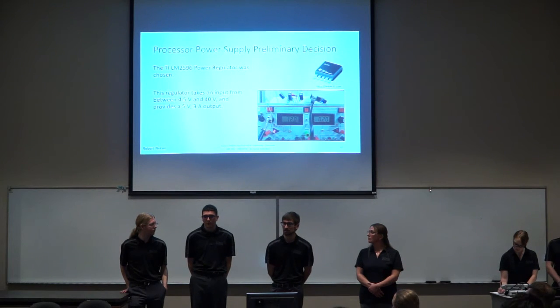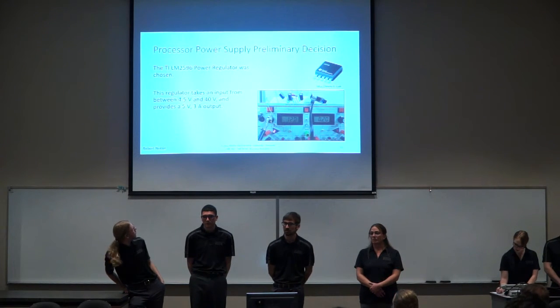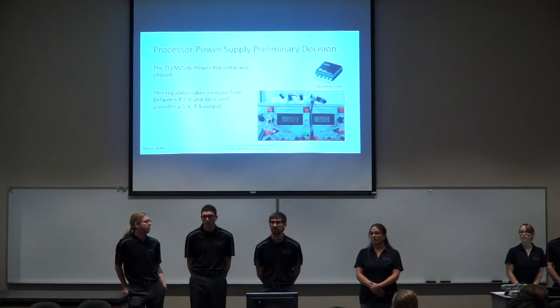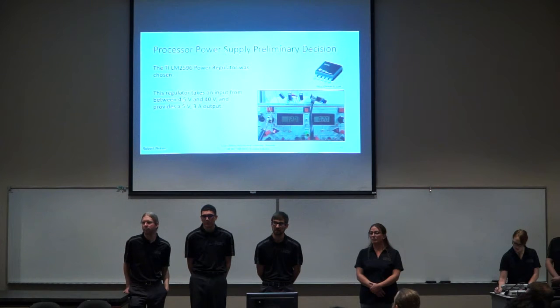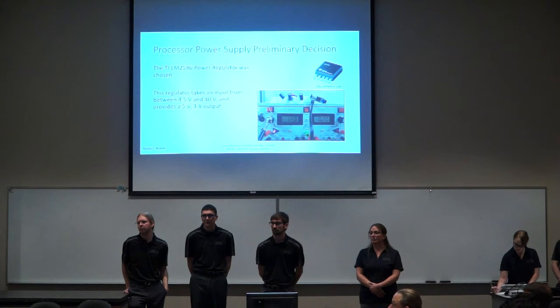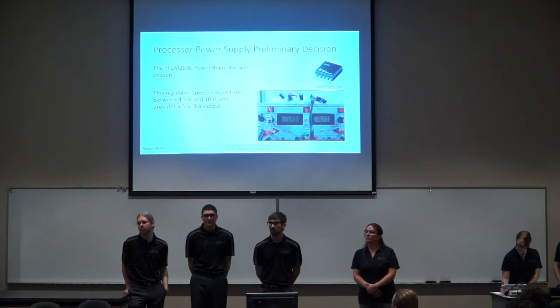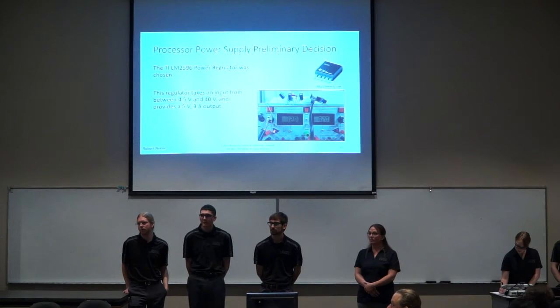In this photo, you can see of the part itself, there are pins in the front, and in the back is actually an area to attach a heatsink to. So they designed it to be compatible with the heatsink. Okay, and have you done any calculations to determine whether you need that heatsink or not? Not yet. Okay, so something to consider, because it's going to be absorbing some energy, you might need a heatsink.